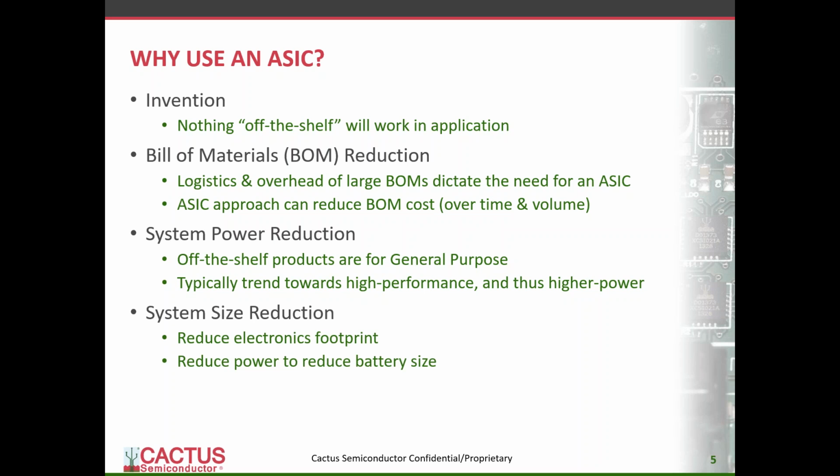System size reduction, again, if you can integrate a number of components into a single ASIC, you're going to reduce the size. Also, off-the-shelf components may just have unwanted features that you don't need. If you can eliminate those, again, you can reduce the footprint. Also, if you reduce the power, which we just talked about, you have an option to reduce the battery size, because basically the power often drives the size of the battery or the battery capacity. So if you can reduce the power, you can reduce the battery, you can reduce the size again. So those are very synergistic.